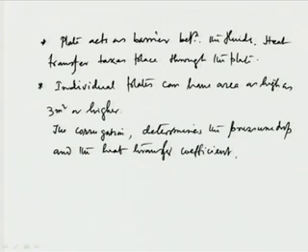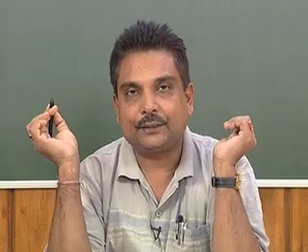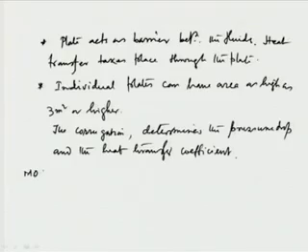As I told, the kind of corrugation increases the turbulence, and as we know, increasing turbulence increases the heat transfer coefficient, but at the same time it increases the pressure loss. Okay. The material of construction for these kind of plates are usually little costly